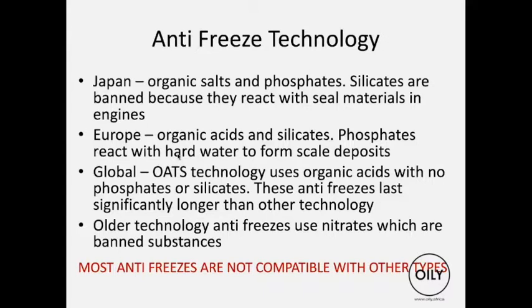Globally, there's OAT technology, which uses organic acids and no phosphates or silicates. These antifreezes last significantly longer, more than twice the lifespan of the other antifreezes.